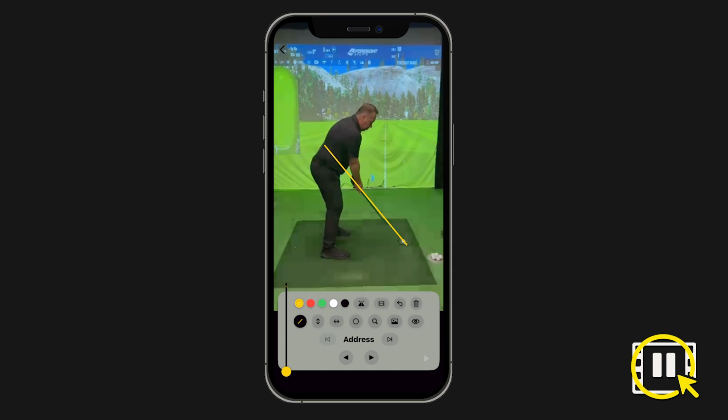If I toggle to clip mode and I put on an image, and I'm going to put on the pre-included logo, if I click and drag, I can resize it in the position that it will stay on persistently. So if I click to the next phase, we will see that the line disappears, and if I come back, then the line reappears.